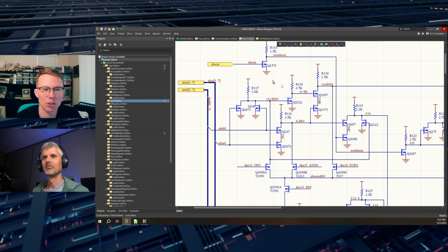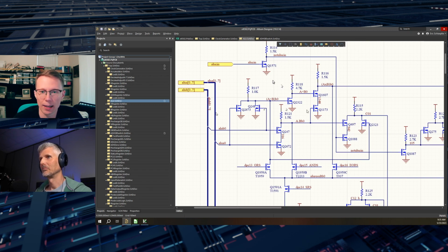I mean, you can, it just takes extra cognitive load to look at it and understand what's going on. Whereas here, with every transistor drawn out, even though it's transistor level, not gate level, you can look at it and realize, oh, we've just got some NAND gates here and some NOR gates and a couple of 3-input gates and so on and so forth. It's not terribly difficult to understand what's going on.